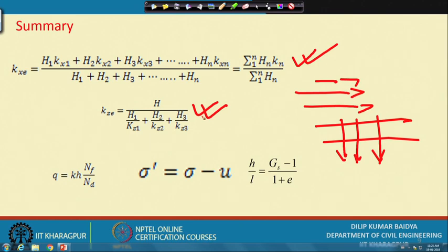And when flow is taking place through some earth body, which is generally not permitted, but if it is taking place, then sometimes we need to find out the quantity of flow, and one of the most well known methods to find the quantity of flow is by drawing a flow net.